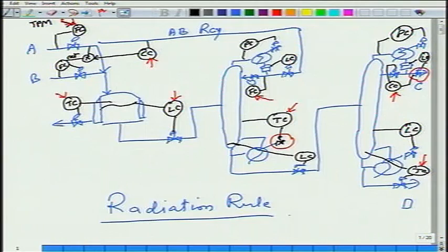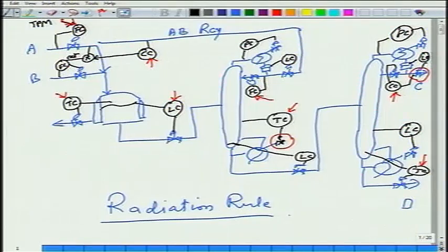So even though my throughput manipulator is at the feed, by adjusting these temperature and compositions, I am ensuring that my product quality is 99 or 99.9 or whatever it is that I want it to be. The point is, this throughput may be 100, 150, 200. The way I am managing the reflux and the reboil in these two columns, it is guaranteeing me good quality.